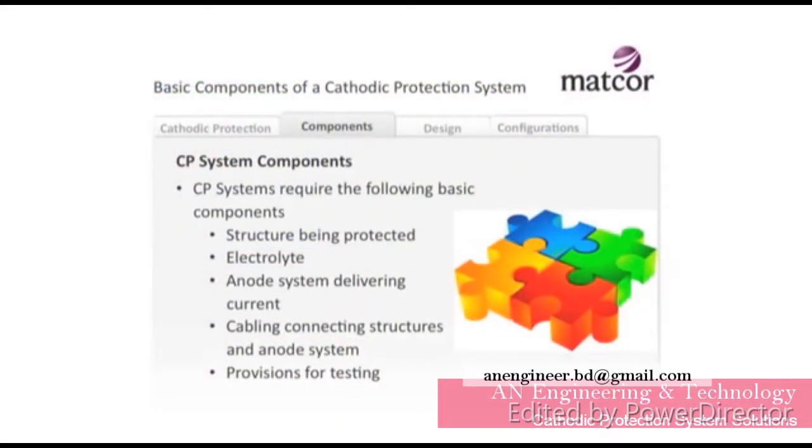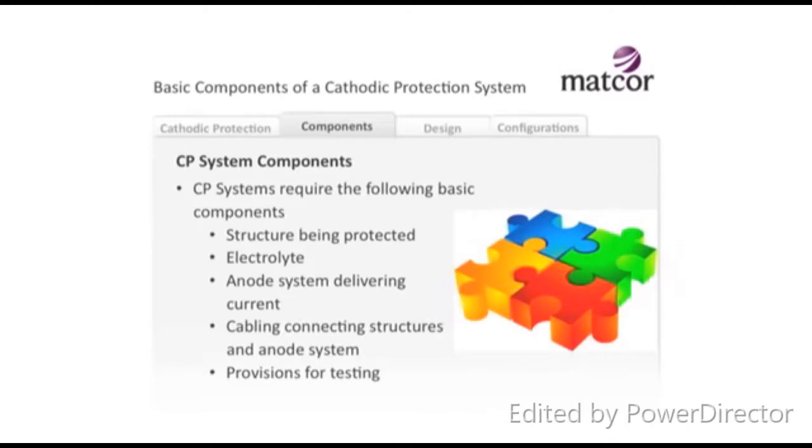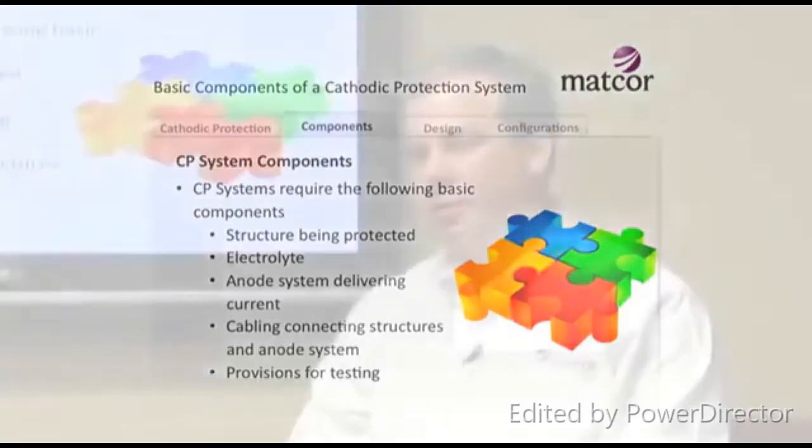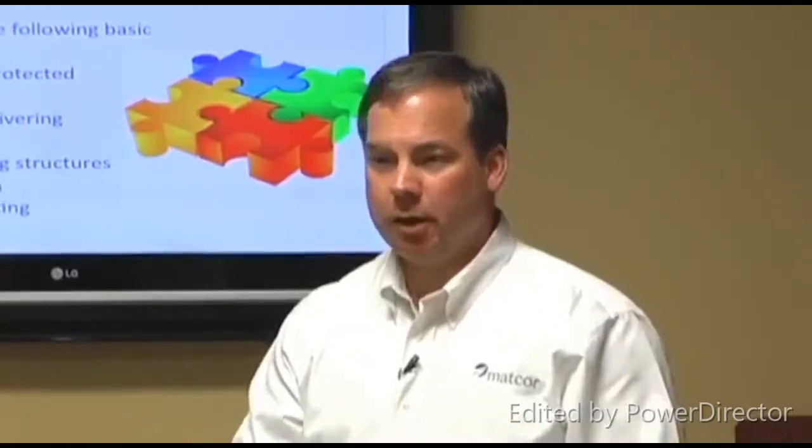We don't do well with atmospheric applications because the air does not allow the conduction of electricity. But we're great if you've got something in water, seawater, or soil. And most of our applications are in those 3 electrolytes, or 2 electrolytes. The other one is concrete. We actually can protect metal in concrete like reinforcing steel.